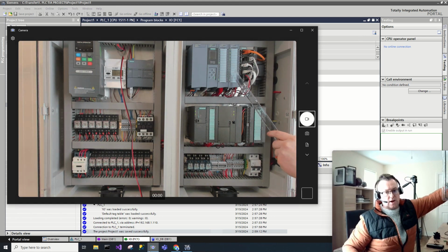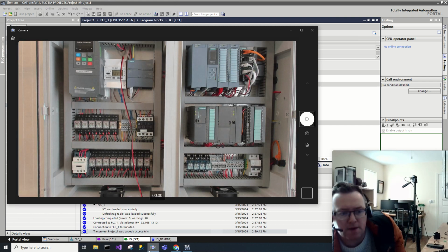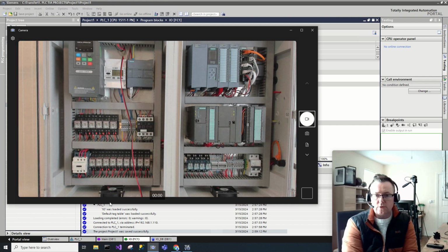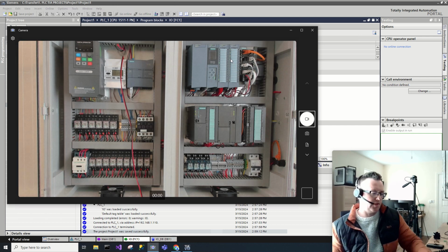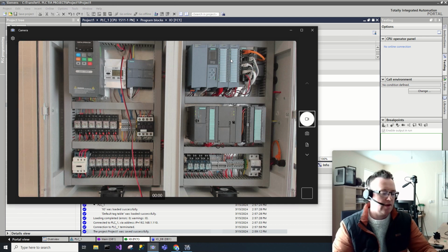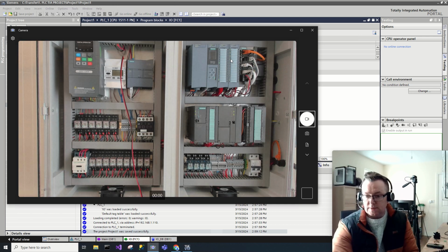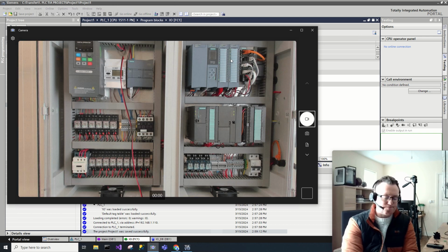So this particular card is focused on digital inputs, and if I want to actually look at it in a variable sense, I will see here, it's very hard to make out, but it basically says channel number 6. So if I turn this proximity sensor on and off, you'll see where the mouse cursor is there, a light begins to blink. If you look into the screen, that tells me what channel the wire is terminated into.